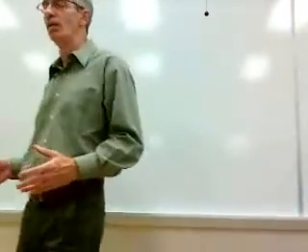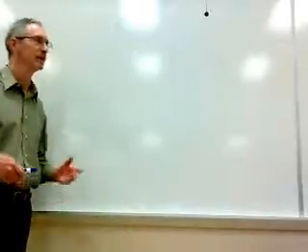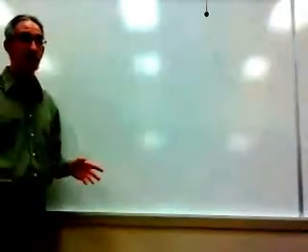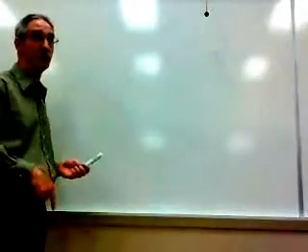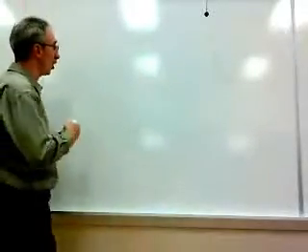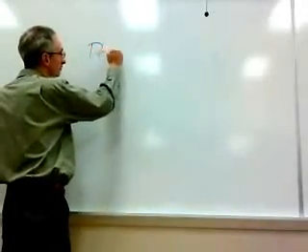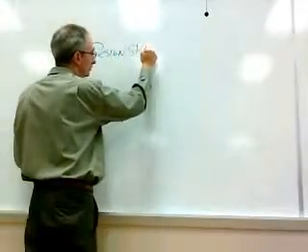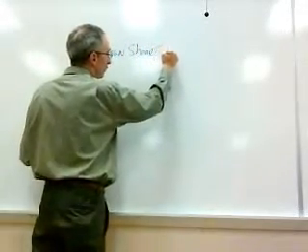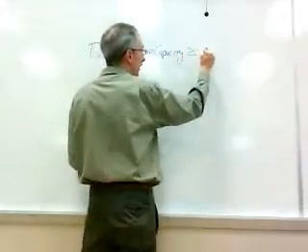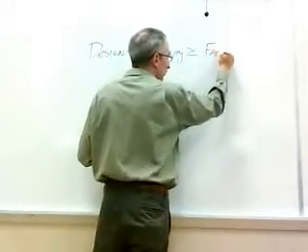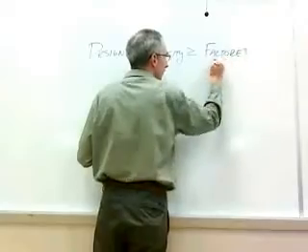You already know what the strength design philosophy is for bending moment. Design moment capacity has got to be greater than or equal to the required moment or the factored moment. Same sort of deal with shear, except instead of saying moment, we say shear. So we can say design shear capacity of my beam greater than or equal to the factored shear or the required shear.